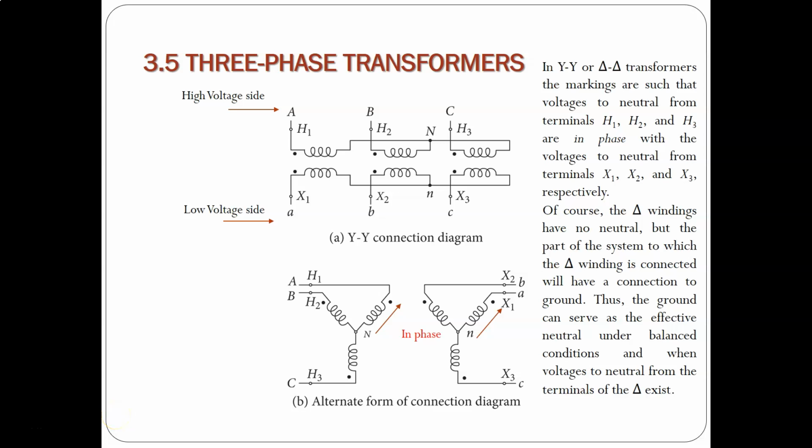We will now talk about the three-phase transformers. The three-phase power is transformed by use of three-phase units. However, in large extra high voltage units, the insulation clearances and shipping limitations may actually require a bank of three single-phase transformers connected in a three-phase arrangement. The primary and secondary windings can be connected in either Y or delta configuration.